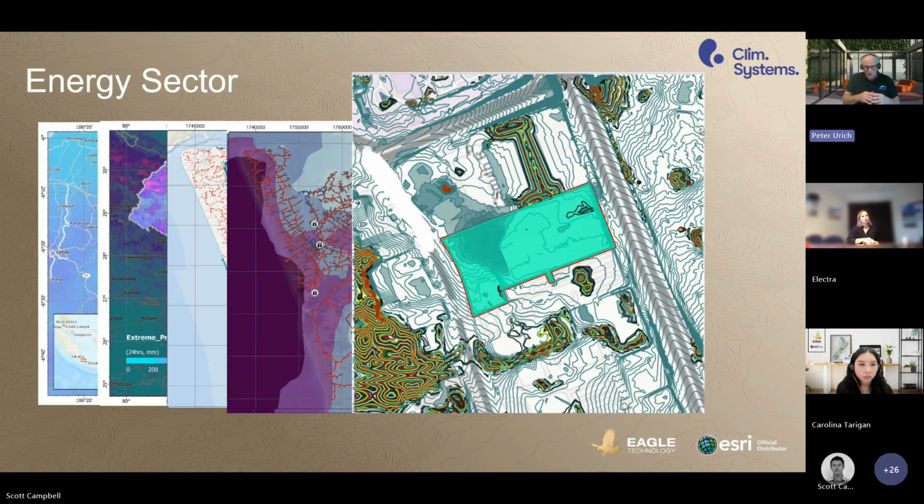Here's one from Nepal we're working on now for a run-of-river hydro scheme. Again, they need catchment level rainfall information. We have access to certain historical rainfall data. We can map that. Scott, the next one, that's a baseline. And then future potential extreme rainfall for that catchment. So we can use all this sort of data where you can, this is spatially provided here, but you can extract that data out into Excel and so on. But we have all those future patterns.